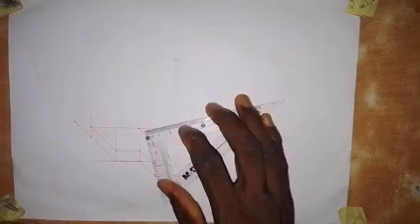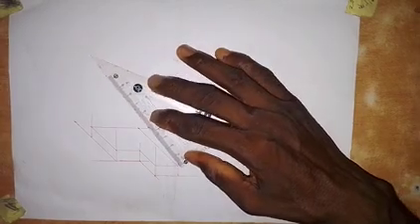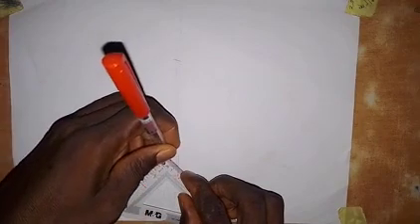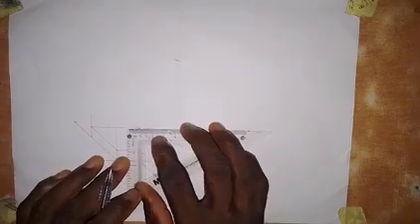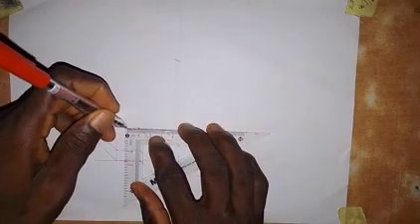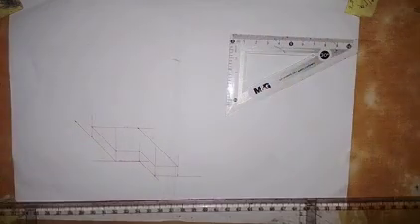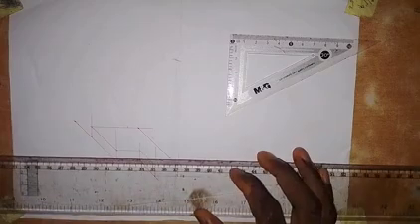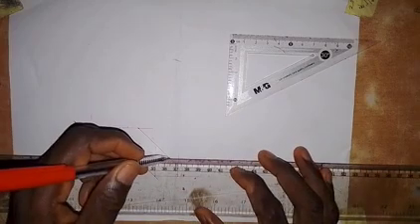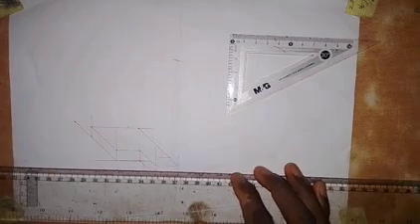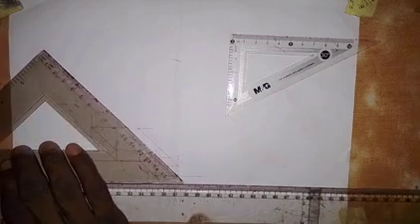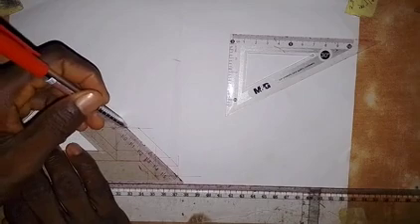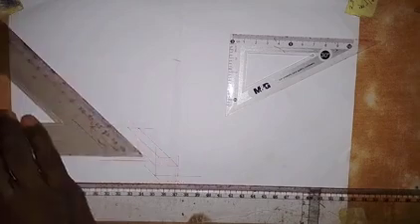So I'm going to quickly do that. Here we take a measurement. So we come onto this line here. Okay, let me take it from here. So we take 10 millimeters. From here, we come to this end. From this point, we take 10 millimeters. Then here we are going to draw a horizontal line like this, and then at this point we have to transfer this distance here. All right, so we have that.